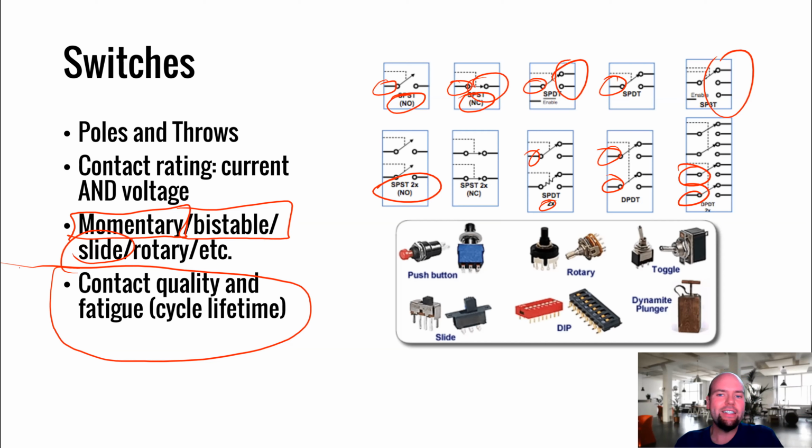And I have a lot of students say, why does the voltage matter? The switch doesn't care what voltage it is. The only thing that matters for a switch is what current's flowing through it. Because if it's a tiny little thin switch, it can't handle a lot of current. And I'll say, yeah, the current rating of a switch matters, but the voltage rating matters too, because when you're initially closing or initially opening that switch, the voltage that you have is going to make a big difference. If you have a really high voltage, you're going to get a lot of arcing current, and that's going to generate a plasma. It's going to do damage to the surface if the surface isn't made of a material that can handle it. So voltage rating matters too.